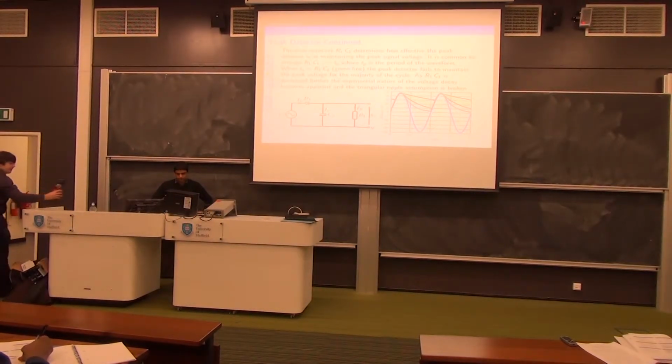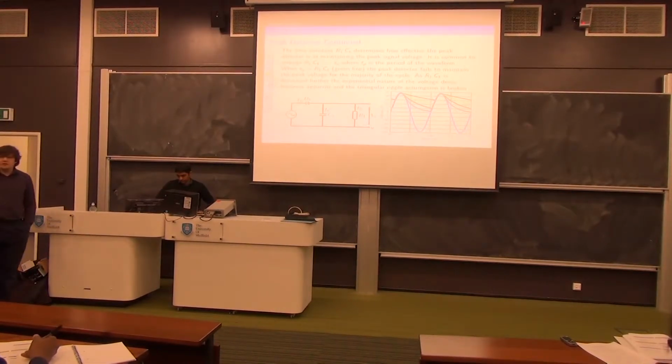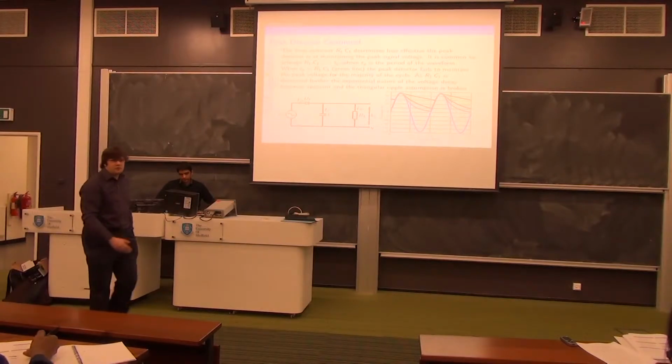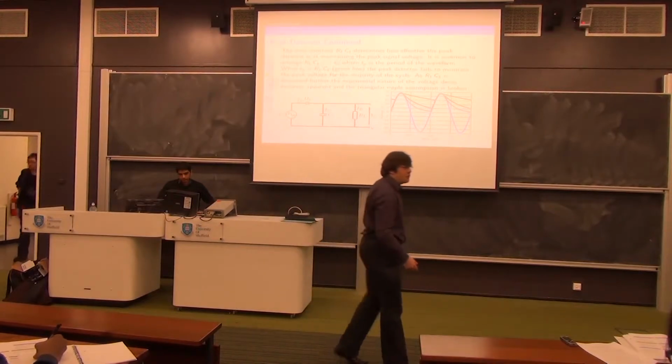The reason is the time constant's the important thing. You can have a megaohm and a microfarad and get a time constant of a second, and you can have 10 megaohms and 100 nanofarads and get a time constant of a second. It's the time constant that's important.